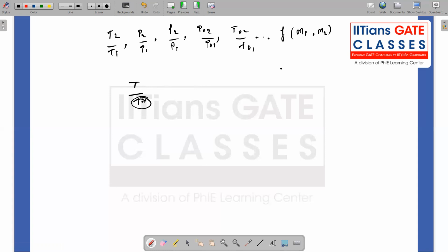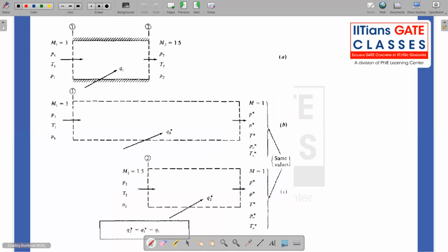The unique thing about the Mach number reaching unity is that whatever your upstream condition may be, there is one unique point at which your Mach number reaches unity for given gas properties. For a calorically perfect gas, you are going to reach one particular unique point. So usually we use a Mollier diagram, like an HS diagram or TS diagram, to analyze it. Let us see this problem, the bigger problem, in a more pictorial way.